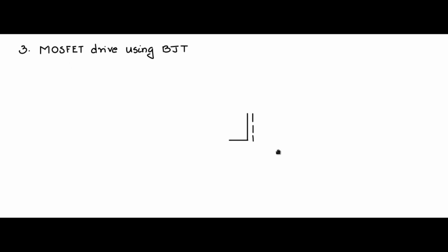I will draw the MOSFET, drain connected to the external load, source connected to the ground, there is a body diode, and we need to monitor ID, the switch drain current. The gate drive is the one resistor R1.